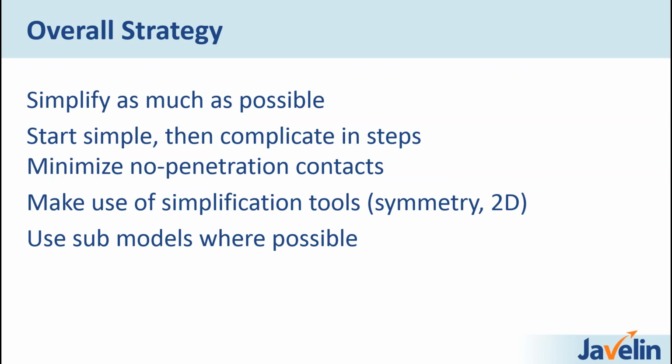Also adding connectors, complicating restraints, complicating loads, etc. When you start very simply and add pieces every step of the way, it becomes very easy to troubleshoot. When something fails, you know exactly what it is, as opposed to wondering which of these 10 loads or 10 contact sets or 10 mesh controls is the source.